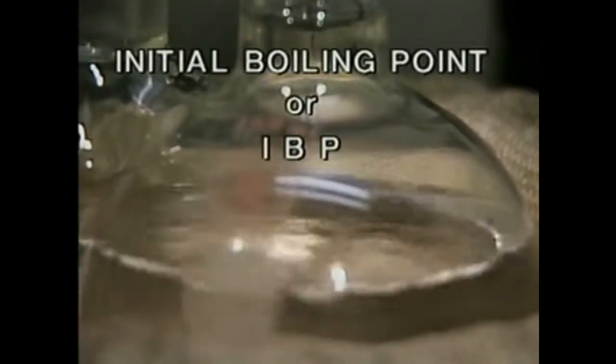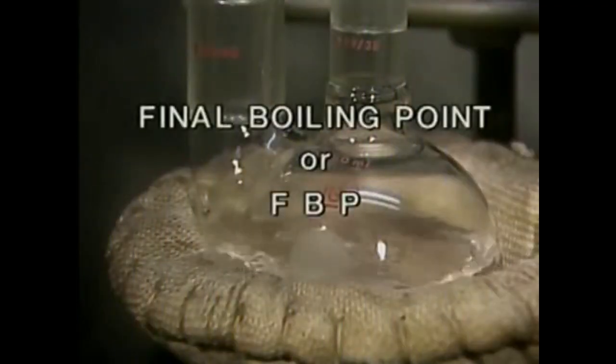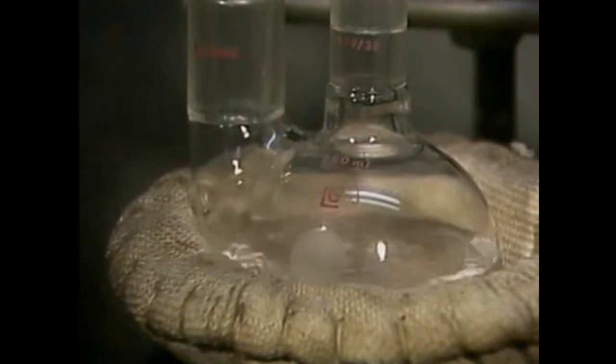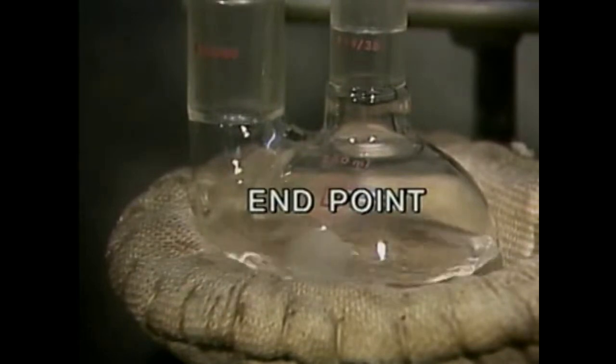The boiling point of the component in the mixture that boils at the lowest temperature is the mixture's initial boiling point, or IBP. The mixture's final boiling point, or FBP, is the temperature at which the component that has the highest boiling point boils. The final boiling point is also commonly referred to as the end point of the mixture.